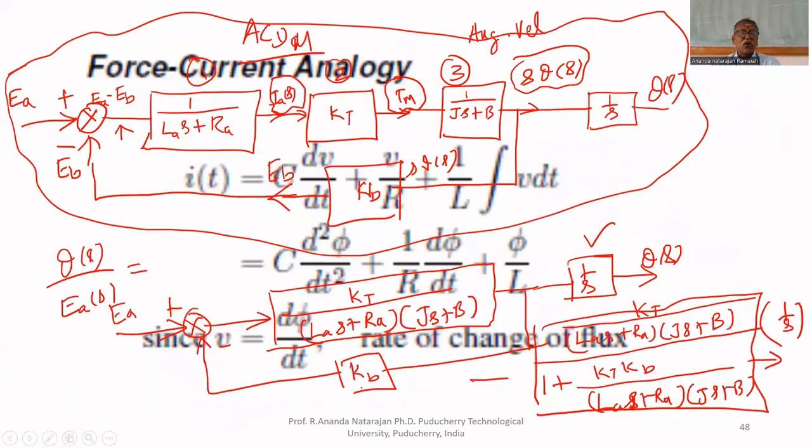If you draw a block for each equation, combine them like this and simplify the blocks, you will get the transfer function. Therefore, if it is mathematically so difficult, then you can represent each equation by each block and combine them like this graphically. Then you can find the transfer function finally. That is called block diagram reduction technique. For that, some set of rules are there.